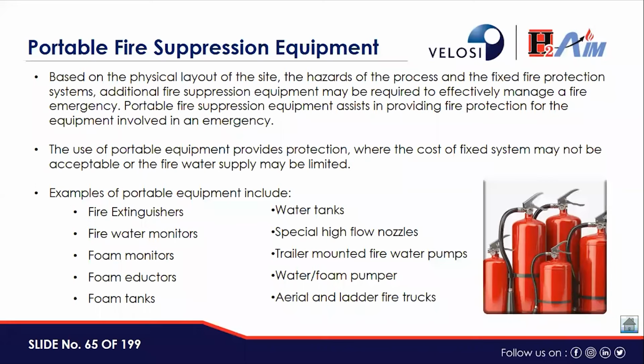Examples of this portable equipment include fire extinguishers, fire water monitors, foam tanks, foam eductors, water tanks, special high flow nozzles, trailer mounted fire water pumps, water foam pumpers, aerial and ladder fire trucks as well. The use of this portable equipment provides protection where the cost of a fixed system may not be acceptable or the fire water supply may be limited.